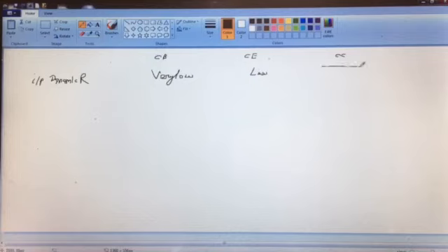We will neglect the common collector configuration because there is no need to study it. It will be of magnitude 50 ohm, 49 ohm, and 1 kilo ohm. That means the input resistance of common base configuration is less than that of common emitter configuration.